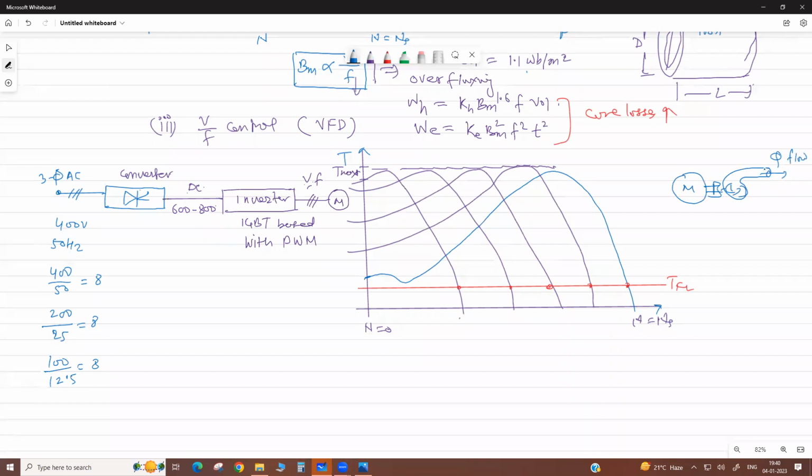You want to control the flow. So earlier we used a valve or damper here, then we add the resistance, and your motor takes the same power from the supply. But when we use a drive here, VFD, then we can control the speed. So your flow, Q is the flow rate here.